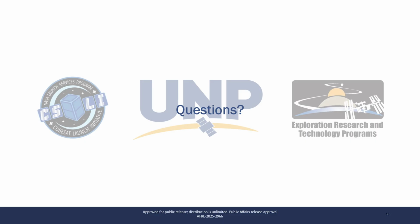Could you expand on what Kalman filtering is? Kalman filtering, essentially, is you have a model based on physics, right? So you're saying, I expect myself to just move in this manner because I know where I am and I know how fast I'm going. So you have your physics-based motion. On top of that, you are also saying, well, my sensors are telling me this is actually my motion, based upon measurements. So the Kalman filter essentially propagates the physics and then takes the measurements and differences those two answers at any given time.